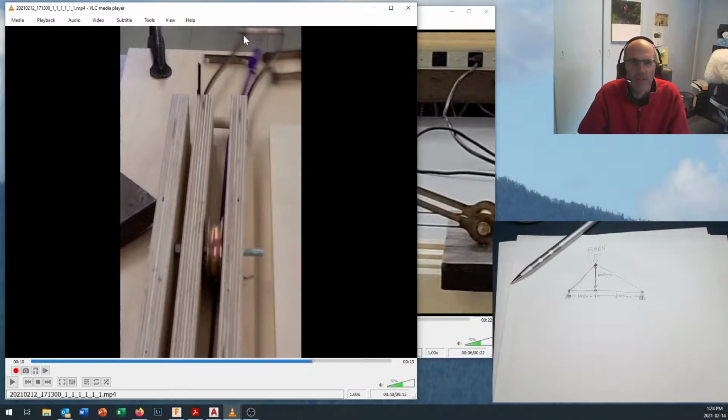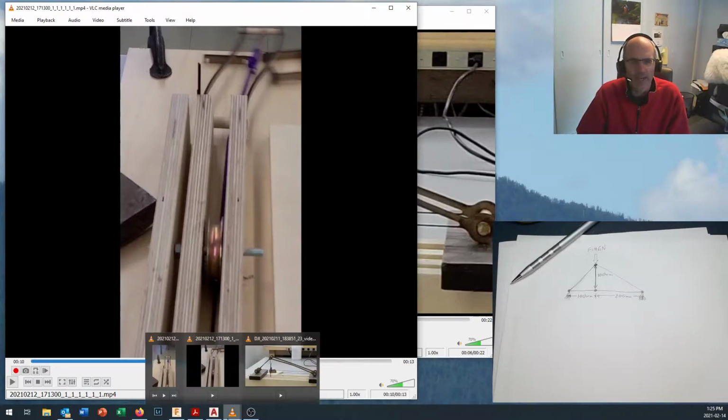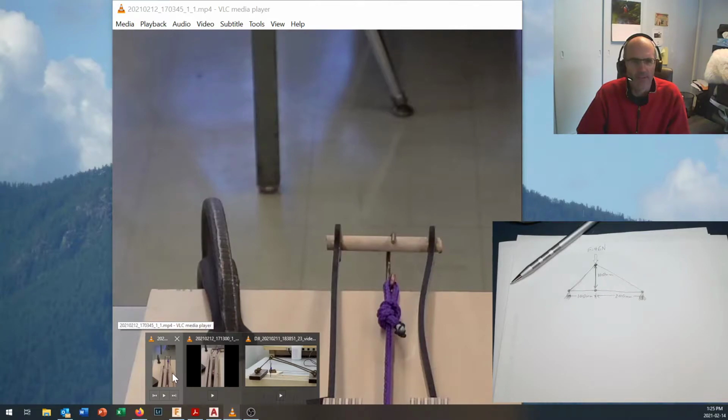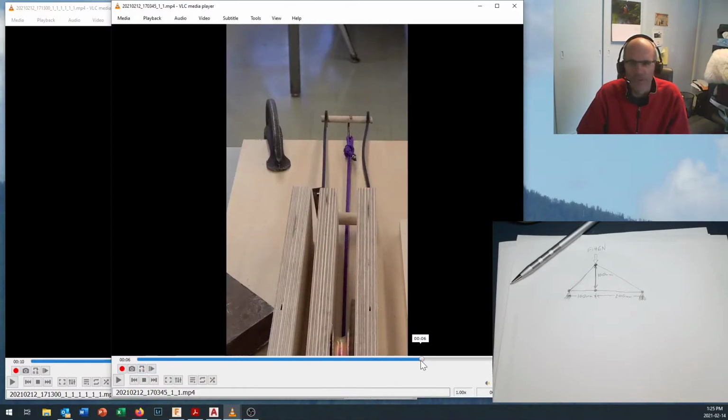And sure enough, if you look right here, you can see those two pieces remain parallel to each other because of the glue holding them onto that piece of dowel. They can't flex from side to side, so they're not truly pinned in the direction of failure. They're actually fixed in the direction of failure, giving us more of an S shape, but it's not really an S, rather than that C shape that we saw when we were doing it with the compression testing jig. So our end conditions in the truss are a little bit different. Now, what was really interesting was that this mode right here failed at really close to 9 kilos, 90 newtons. I've got another one right in here of another mode of failure that comes along in here.